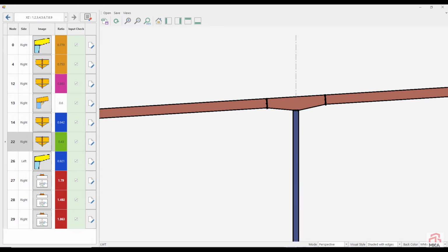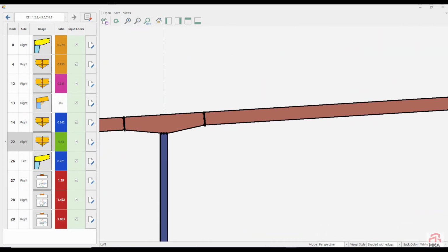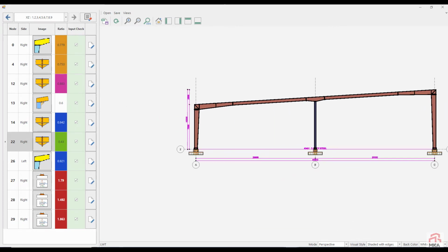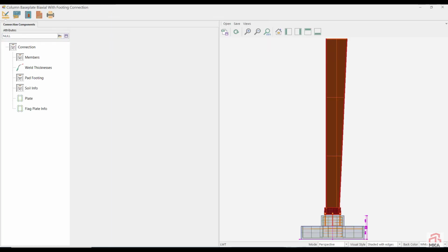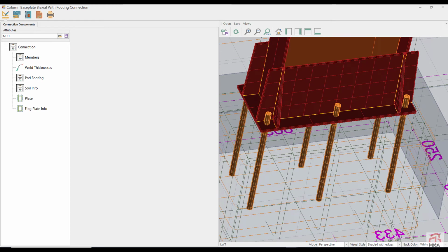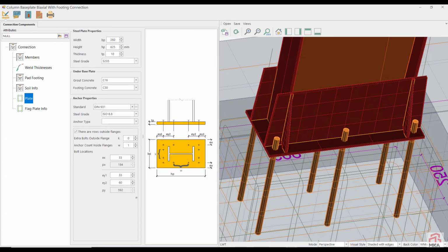Now let's redraw our construction model. Our splices have arrived, our other column beam splices have arrived. We have now calculated the connections of this axis. Now let's come to the column base. These column bases are rigid. We can solve it together with foundations. When we look at it, it seems like the plate is a little narrow. Let's enlarge this plate first.